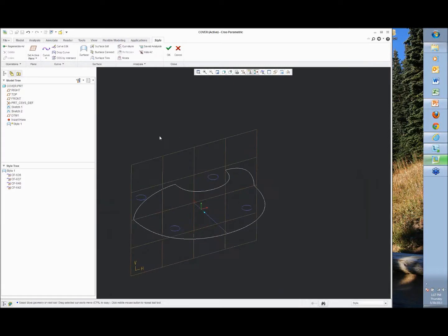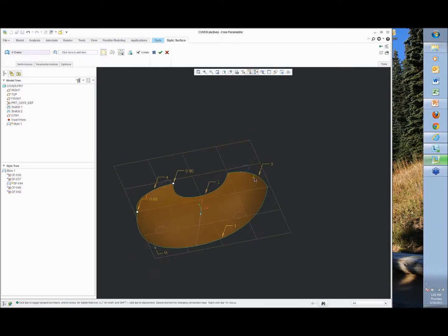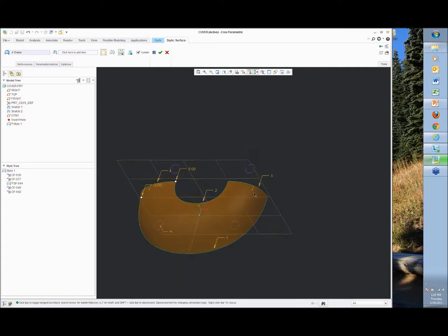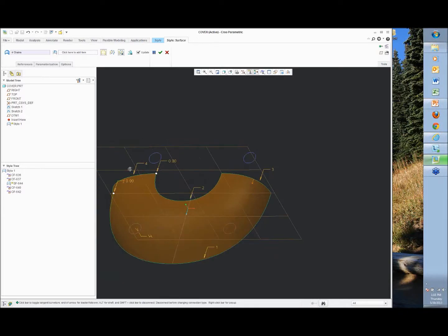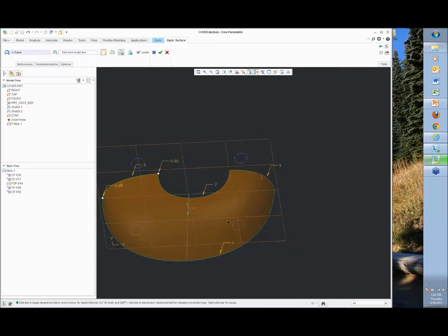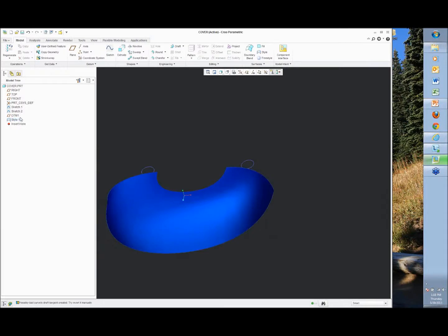So I'm adding curves, now I want to add a surface. Start the surface tool. Inside the feature, right? So this is still all within one feature now. At the bottom, use the control button, so I get all 4 of them. That's my normal icon, so as long as I'm normal there, because when I mirror this to the other side, I want a nice clean surface when I'm done, so I want to make sure that's all nice and normal. There's my surface. Finish the feature, and you can see all of that is now built within that one feature called style.